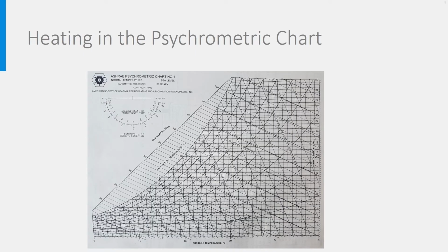If we look at the process in the psychrometric chart, we see that heating at constant absolute humidity goes to the right, and the enthalpies can be read here. So, you see some small differences in the absolute values when compared to the Mollier diagram, but this has to do with the precision of the graphics and the goodness of your eyes. The enthalpy difference is identical.